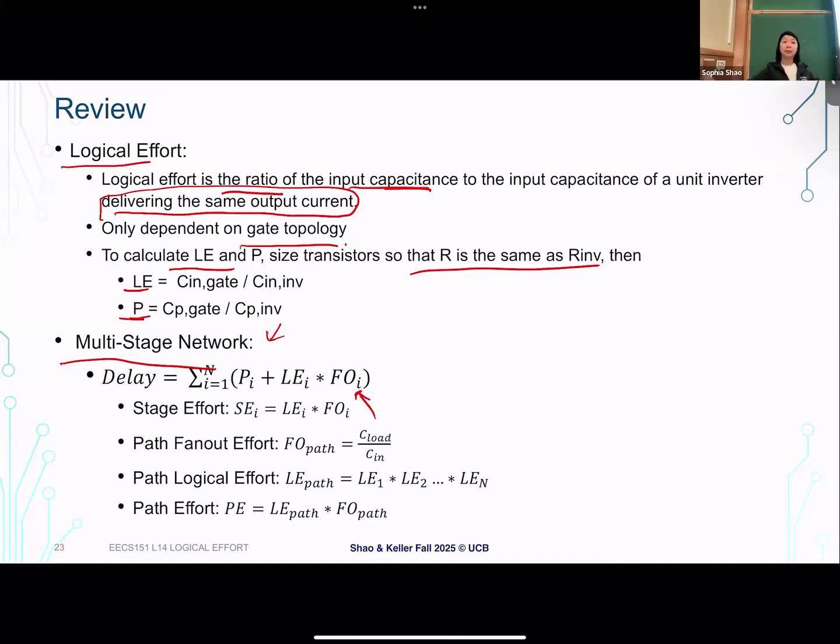We get the minimum delay we want, and we can work either forward or backward to think about how big the transistors need to be. So there's a lot in this lecture. I hope you find at least a symmetry with what we did with the inverter delay, but now with additional logical effort, so that you have another mechanism to think about more complex gates.